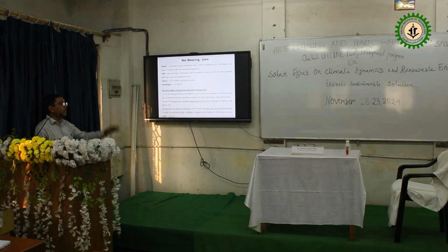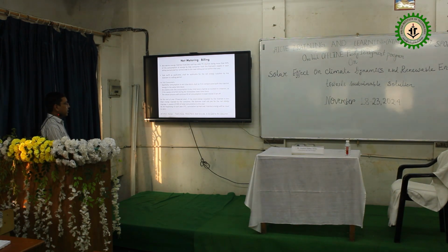According to that, net metering or the different metering processes, gross metering or net metering, will be done. Commissioning may be allowed with metering by prosumers, with load up to 500 kilowatt and up to the sanction load, whatever it is as per the consumer's requirement, as well as state energy commissions, and they will do the survey accordingly.